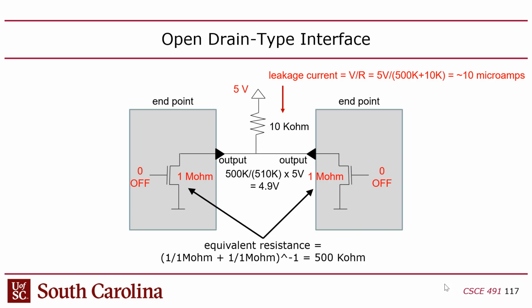Except UART's push-pull, but still it has a default state of 1 for some reason, right? But I don't know if there's a technical reason for that. But in I2C, there is a reason why the default channel value is a 1, because of that pull-up resistor, right? And that pull-up resistor can be internal or external. On these boards,